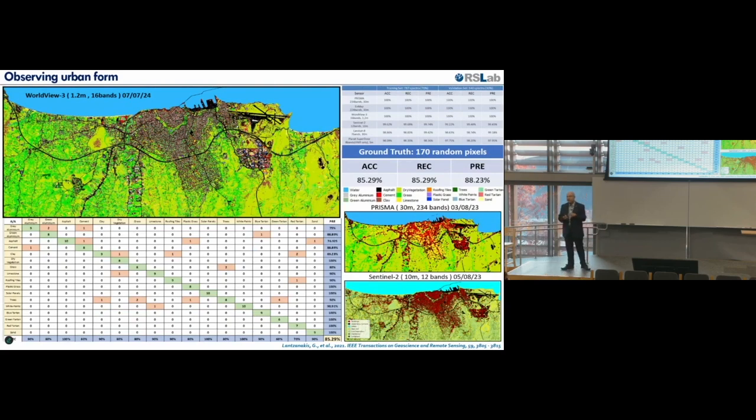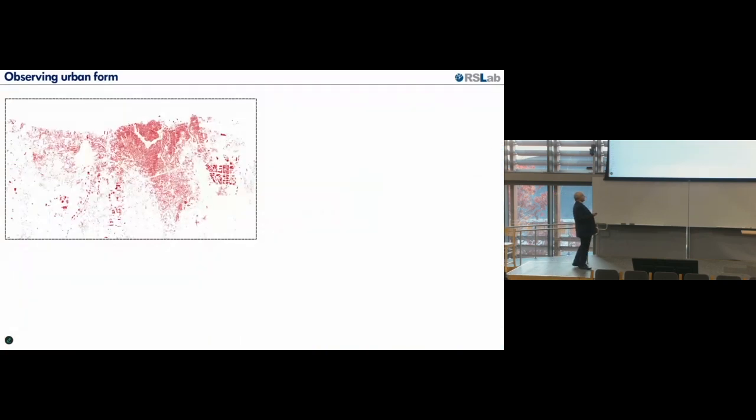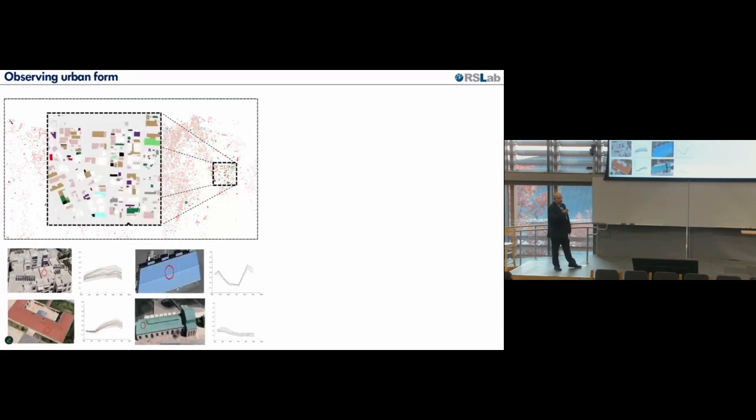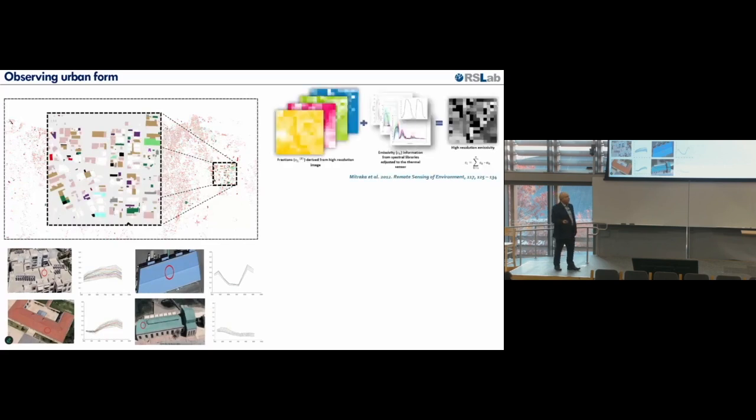But important here is that these classification algorithms are trained by our spectral library, not image-based. So we don't collect image-based samples to train our algorithm, but use the spectral library directly, and that means we can implement it in any city. So we have the buildings and also spectral information for the roofs, for example, and we can employ our spectral mixing algorithms to assign emissivity values at facades with specific materials.